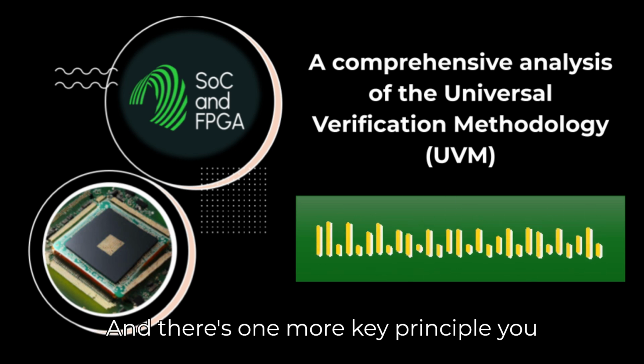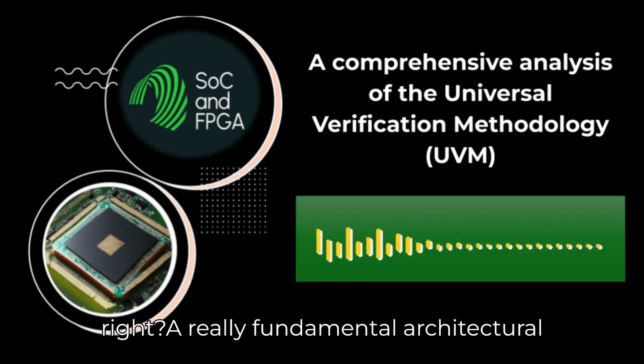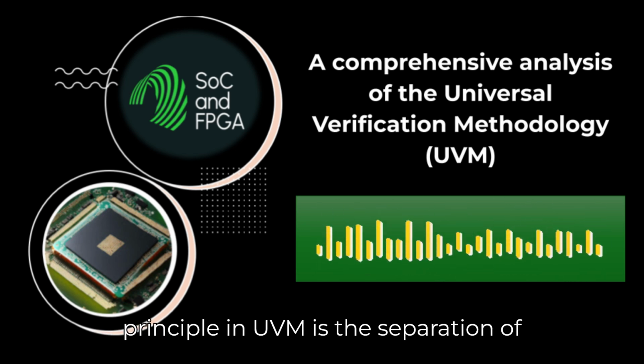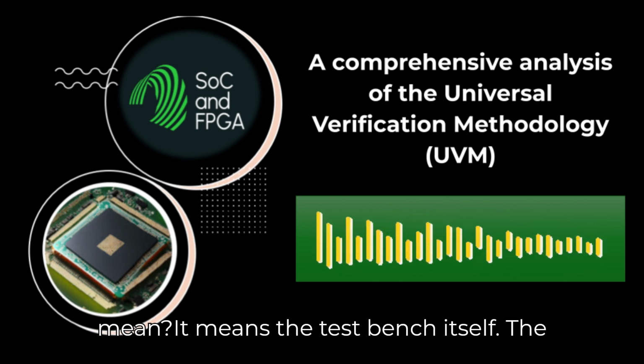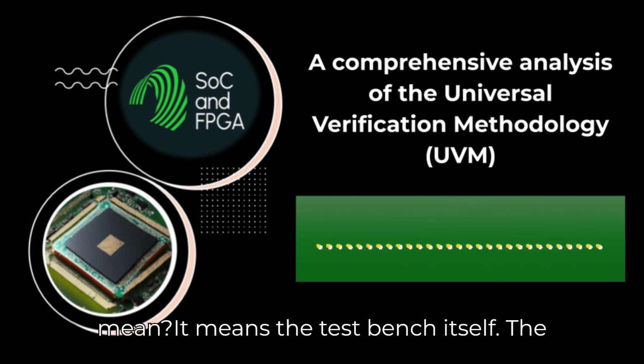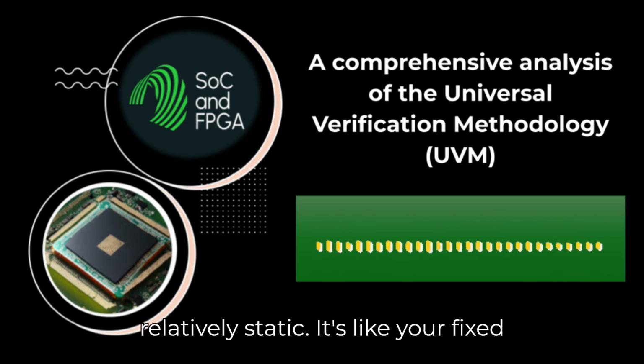And there's one more key principle you mentioned about architecture. Right. A really fundamental architectural principle in UVM is the separation of tests from the testbench. What does that mean? It means the testbench itself, the structure with the environments, agents, monitors, drivers, scoreboard, is relatively static.